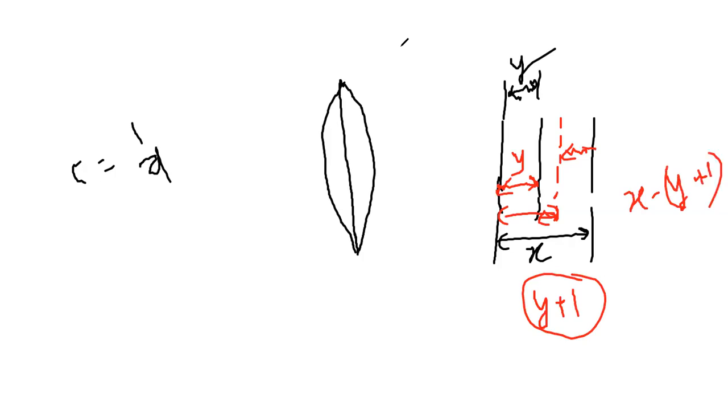So this expression measures the variation in the distance, which results in the change in capacitance. Now, how are these changes verified, or how are these changes reflected based upon the input pressure that has been applied to the capacitive type of transducer? So at the first point, we are supposed to understand the concept that here we are trying to measure the pressure, but the pressure is calibrated in terms of capacitance C.